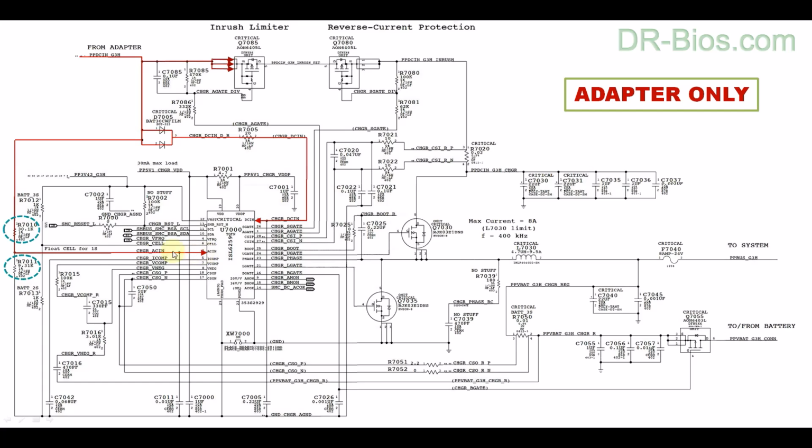And that enters the ACIN pin of the IC, as I said before. And when the IC receives the voltage, it realizes that the right, correct adapter is plugged into the device. I should say that these two resistors have another duty as well, which I'll talk about in the adapter section.